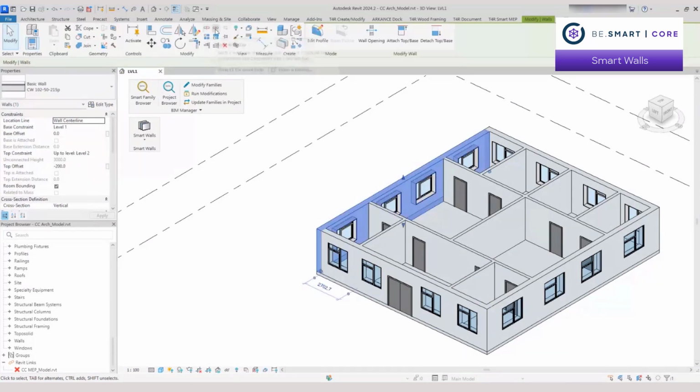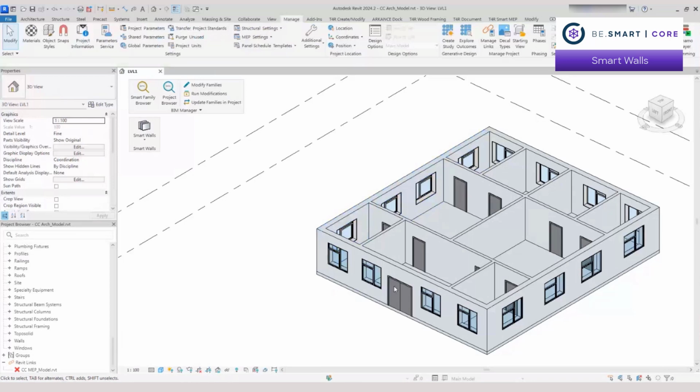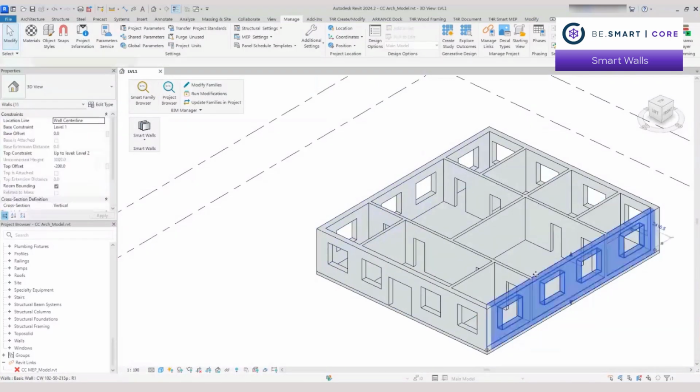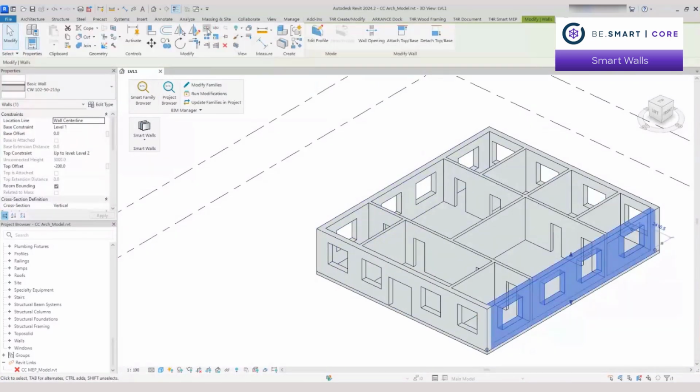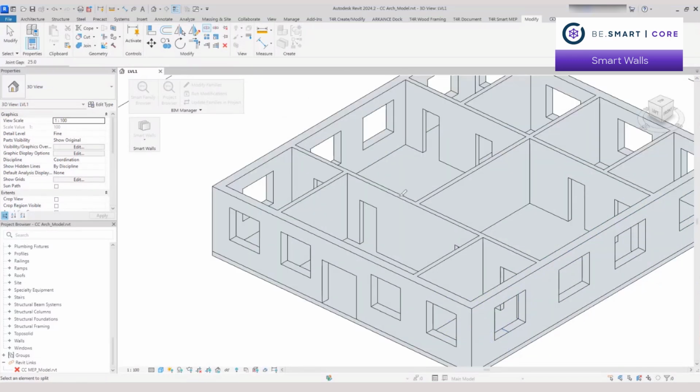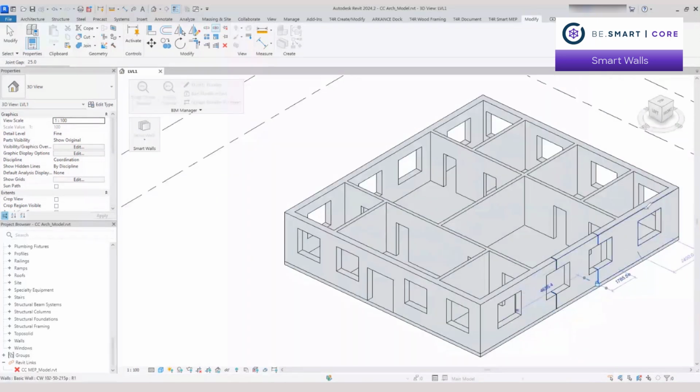This one, there's a split element or split with gap. And for this procedure, let me hide doors and windows. Hide in view. Let's do category. If the user would need to split, he can use this functionality, of course. And let's say here, as an example, I would want to split it in the center of the window. I paste the split. Well, let's do split with a gap. It looks better. It's more visible. Split, split, split.